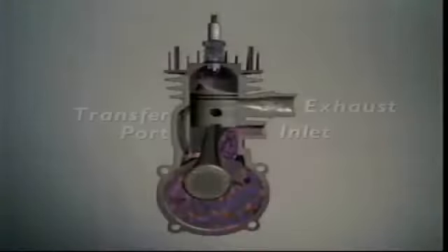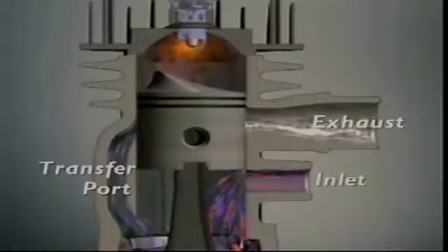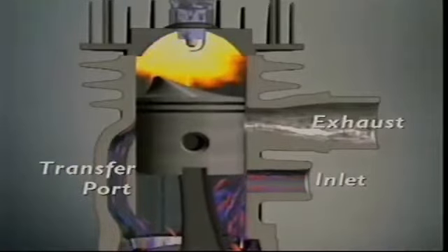At the same time, the rising piston is increasing the volume of the crankcase below the piston. Pressure in there falls until it's less than outside air pressure. This pressure difference forces more mixture into the crankcase. As the piston reaches top dead centre, mixture already there ignites, and expansion of gases starts to drive the piston